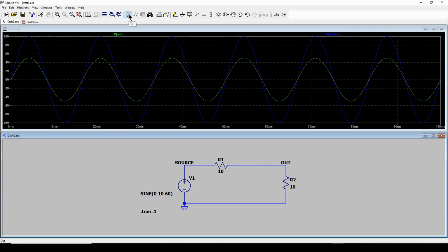Then I'll get my scissors to cut this wire, right click to release, and I'll go up here, and this is a diode. So I will pick up a diode, move it into the circuit, hit Control R a few times to put it in the right direction and horizontal, left click to stamp it down, right click to release, and now I've got my diode.